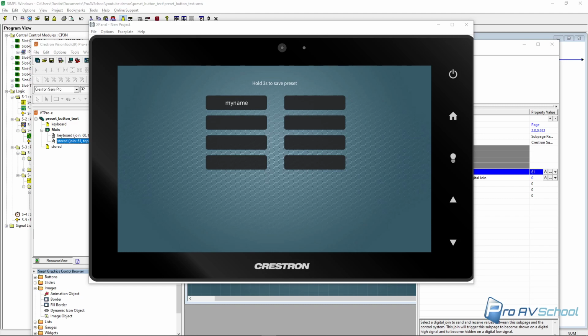In this video, I'm going to show you how to create on a Crestron touch panel a way to save presets or text in non-volatile memory, or NVRAM. What that means is it will hold its values if the processor reboots. So this is a way for users to edit the names of their presets and it will stay if the processor loses power or whatever.